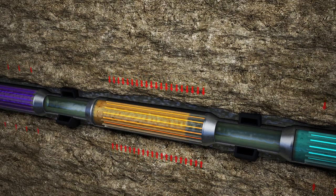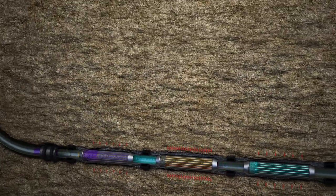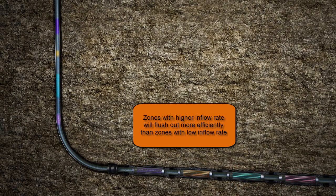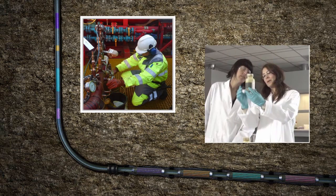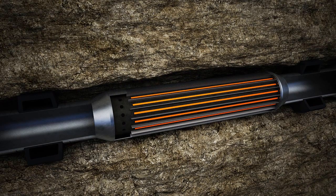When the well is turned on, flow from the reservoir flushes out the small volume of oil containing high concentrations of the unique chemical tracer. Zones with high inflow rate will flush out this small volume of oil more efficiently than the zones with low inflow. This creates tracer concentration profiles in the flow stream that are proportional to the inflow rate of each zone. By taking samples of the produced fluid at the surface, the concentration profile of each of the unique chemicals is determined. Now for a closer look at this process.